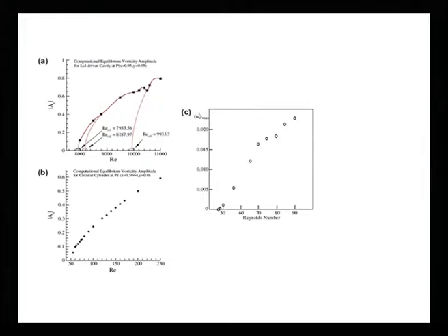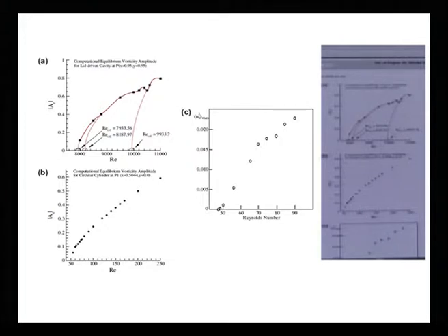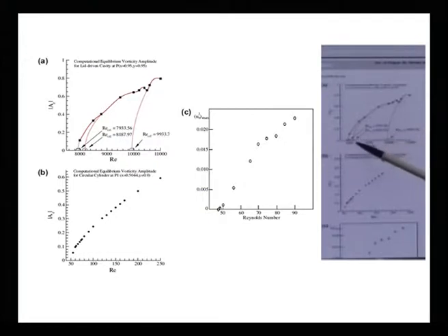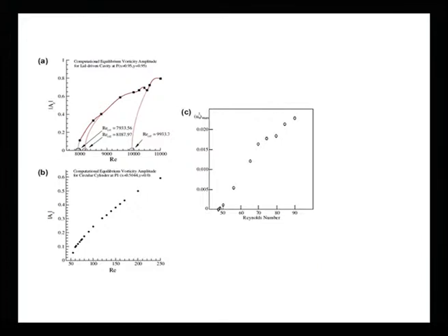As you can see, the first one is around 7,933. The second one is at 8187, and the third one that we have shown here is 9933. So, essentially whatever we have seen for flow past a cylinder is depicted here, and the corresponding experimental results by Strykowski are shown here. You do get to see exactly a similar phenomenon, that it is not purely given by the Landau equation, it falls on various branches of bifurcation, and this of course lends credibility to what we have been talking about in terms of the universality of this kind of instability modes.